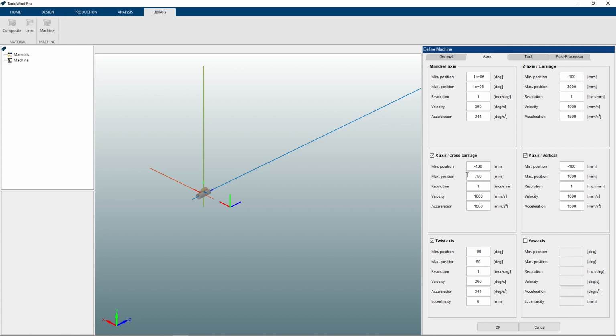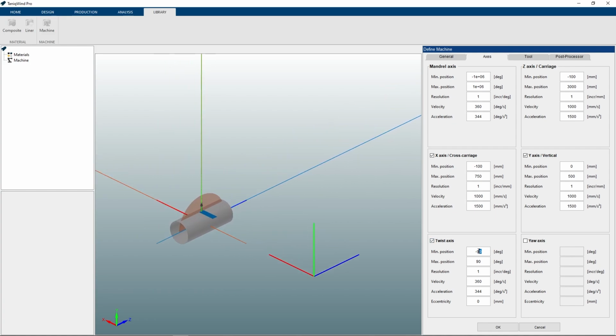The resolution defines the axis resolution and direction with respect to the origin of the coordinate system. The absolute value of the input defines the conversion rate between displacement and the axis increment. The sign of the value defines the axis jogging direction with respect to the aligning origin of the coordinate system axis. For the velocity and acceleration, the nominal velocity and acceleration of the axis should be given as a positive value.